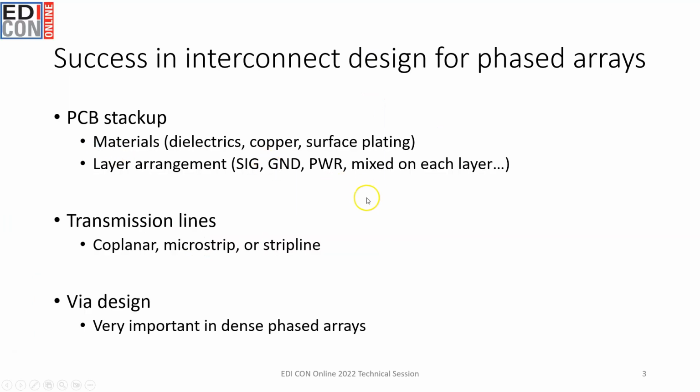But in this particular presentation, we'll be talking about phased arrays, and I'll go over some of the points surrounding PCB stack-up, things like layer arrangement. Those are two of the important areas where successful design will lead to some of the best phased array performance, as well as the best transmission line performance. So we'll talk briefly about the different types of transmission line options, but as you get to higher frequencies, coplanar lines start to dominate.